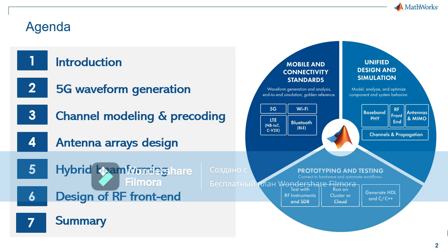The complexity and the power consumption of fully digital beamforming can be mitigated by using hybrid beamforming approaches that divide the beamforming into two modes. In one domain it is the analog, and in the other it is the digital approach.